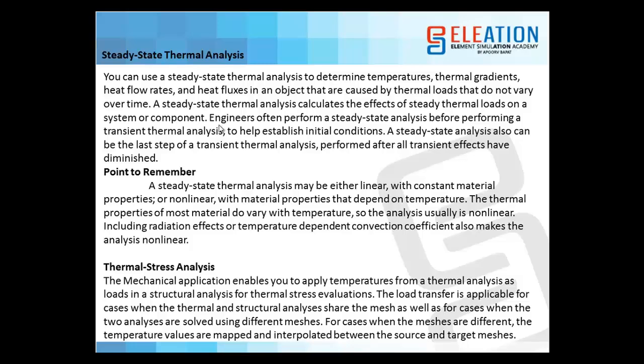One where we consider conduction and convection, and the other where we see the thermal stresses, that is, the temperature, what are the stresses generated or deformation happening at that particular temperature. So in one, we see how the temperature is moving from one component to another and how the heat dissipation is taking place. And in the other type of thermal analysis, we will see at a particular temperature what is the maximum stress and deformation coming on that particular component.